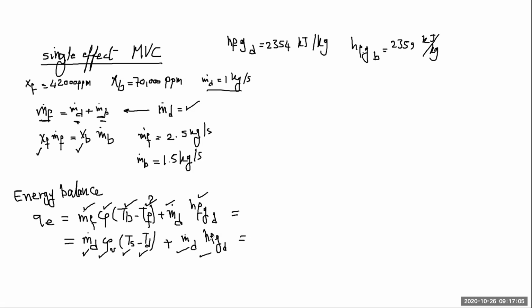So we have all the parameters here in the second line, and accordingly, we can calculate the power, 2360 kilowatt. When we substitute this one here, we can get the value of TF, that is going to be calculated as 59.46 degrees Celsius.